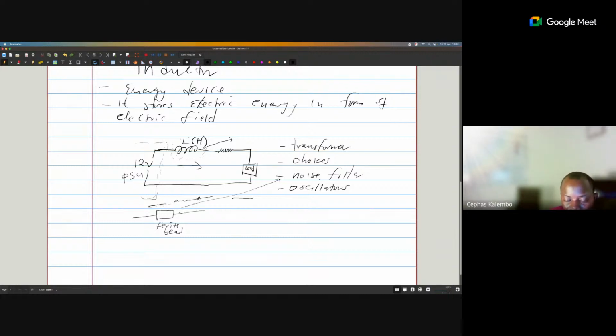So if you are going to buy a charger, always buy a charger that has some kind of ferrite bead, because it prolongs your battery life and the life of the electronics in your phone. That's how this works. When the flow of current is coming from the charger towards your phone, this ferrite bead will ensure that those high spikes like these will be cut off and will not pass through.